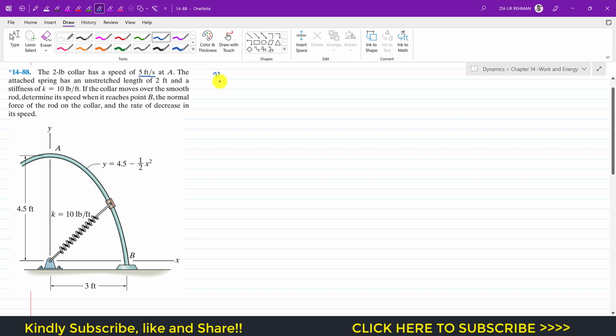So let me write that the velocity at A is 5 feet per second and the unstretched length is 2 feet, and the spring has a stiffness of 10 pounds per foot. It is said that if the collar moves over the smooth rod, determine its speed when it reaches point B. So we have to find the velocity at B.